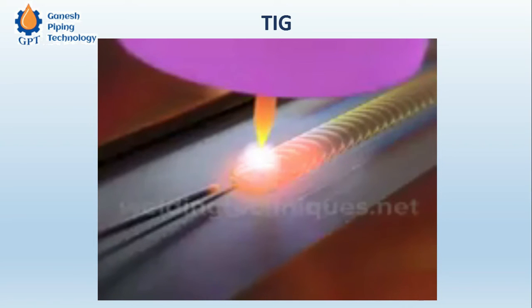The motion of the hand is also very important. If there is a shaky motion, then we will not get a good quality weld. This is important for all types of welding, MMA, TIG, and all except SAW, because SAW is not done manually; it is automated through a machine.